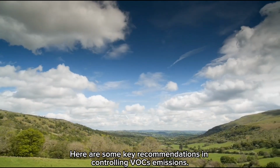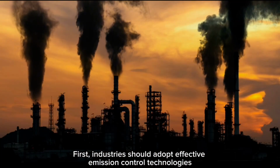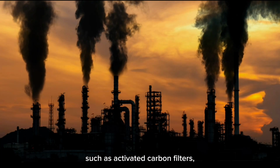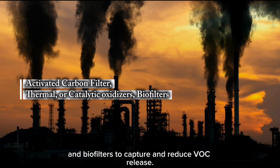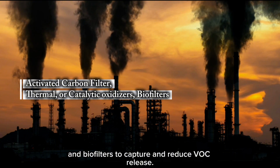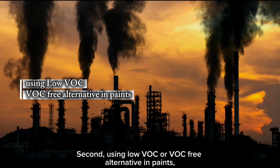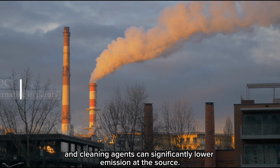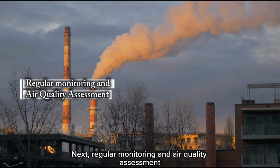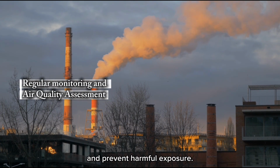Here are some key recommendations in controlling VOC emissions. First, industries should adopt effective emission control technologies such as activated carbon filters, thermal or catalytic oxidizers, and biofilters to capture and reduce VOC release. Second, using low-VOC or VOC-free alternatives in paints, solvents, and cleaning agents can significantly lower emission at the source. Next, regular monitoring and air quality assessment help ensure emissions remain within legal limits and prevent harmful exposure.